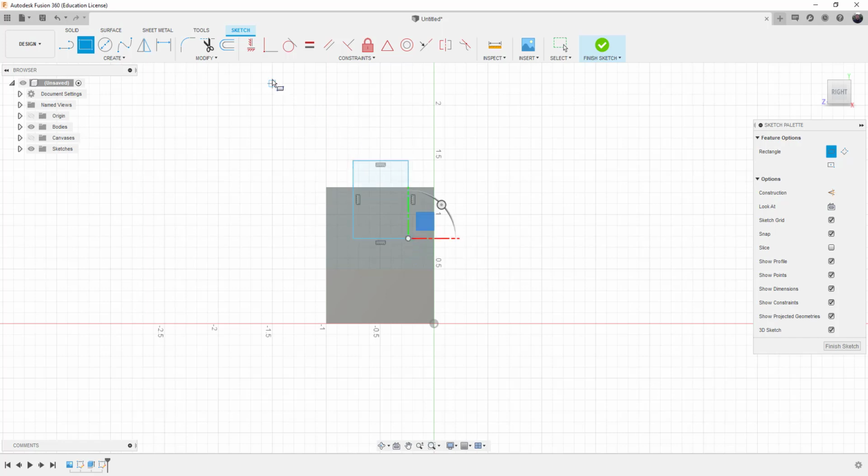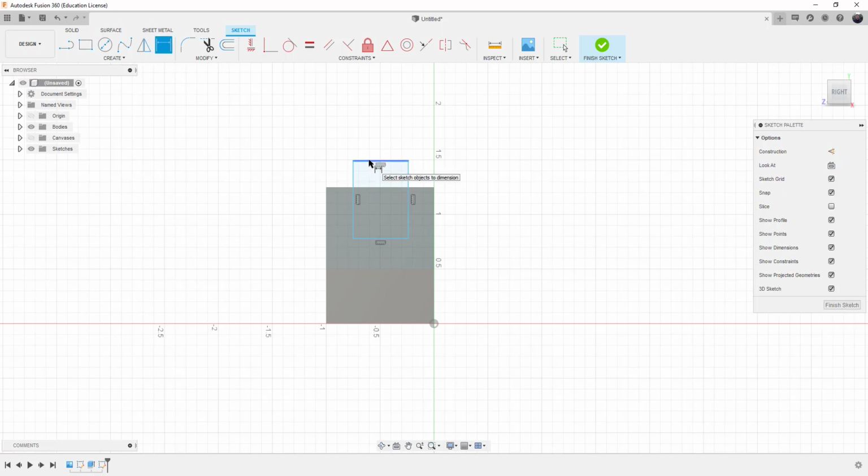Opposite corners. We'll then add dimensions, and so the width of this particular object is 0.5. The depth of this object from here, from the top of the object to the depth of the cutout, is going to be, again, 0.5. But we have to make sure that this cutout is centered. So we're going to need to put a dimension in from the side to the side, and that needs to be 0.250. Boy, I was close on that sketch. And that pretty much guarantees it.